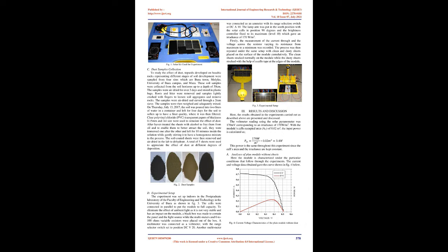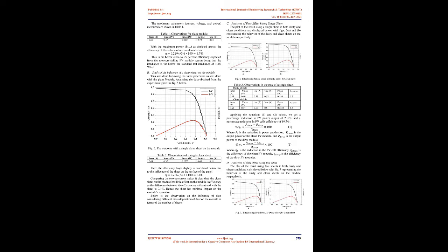A sensor is used to measure the irradiance in connection with a multimeter in the measuring range of 2,000 mV. The measurement of the irradiance is in W/m², where 1 W/m² equals 1 mV. For measurement purposes, the device must be aligned with the sensor field towards the source of light so that the rays fall vertically on the round sensor field.